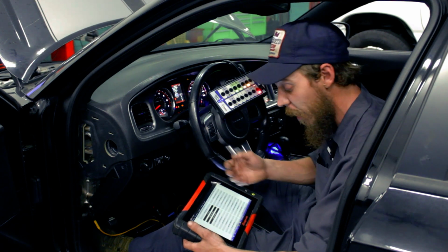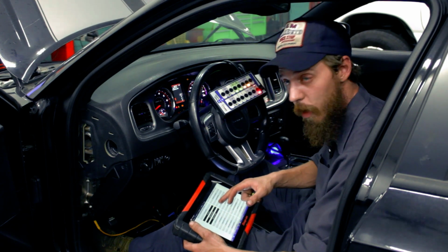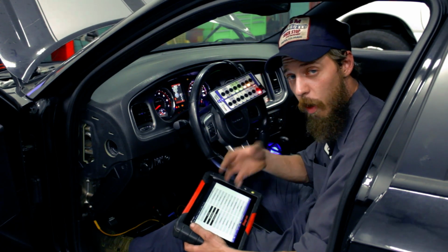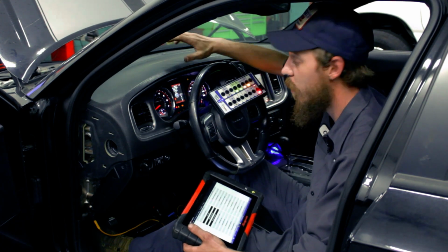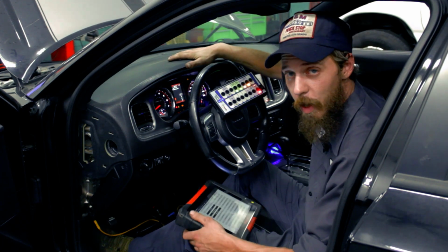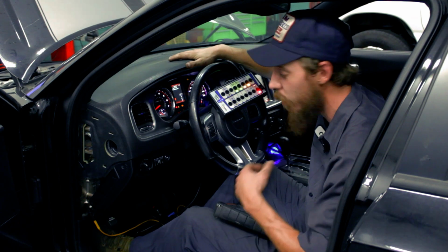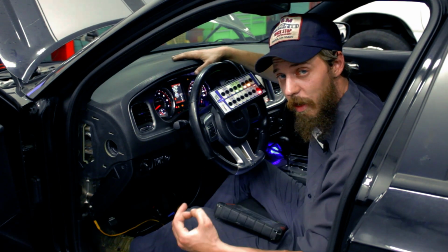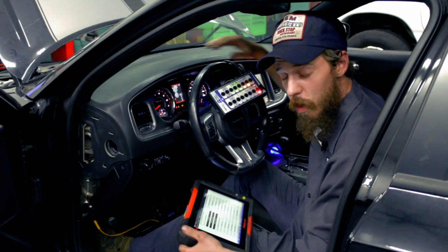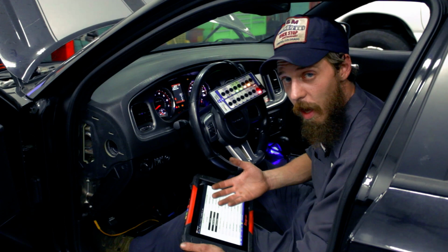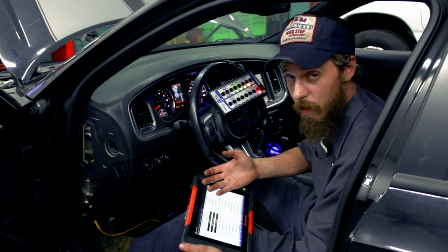Very concerned about that. A PRNDL display request, which is going to be a direct input based off of the range sensor that is then going to communicate to our instrument cluster. Our instrument cluster, which I may not have noted before, does agree with whatever gear selection we have at any given point, so we can feel pretty confident that it's reading correctly, but we have the data PID. Takes half a second to click the button.